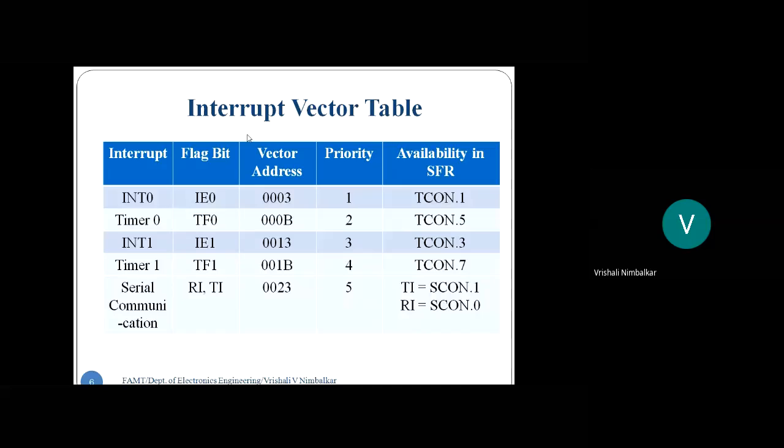Interrupts, where multitasking is possible. The microcontroller can do some other execution, whereas the other operation, when it is completed, will generate an interrupt. A timer can keep on working in the background, and when the timer's 1 millisecond delay is over, it can interrupt the microcontroller. The microcontroller need not wait till 1 millisecond is over.